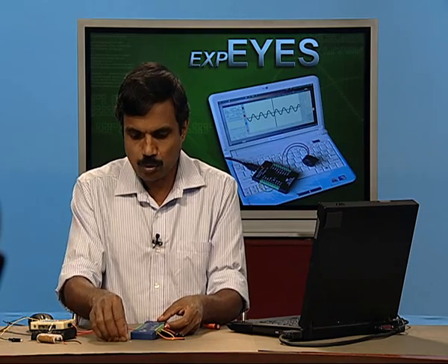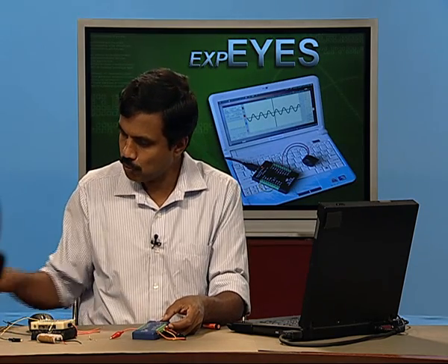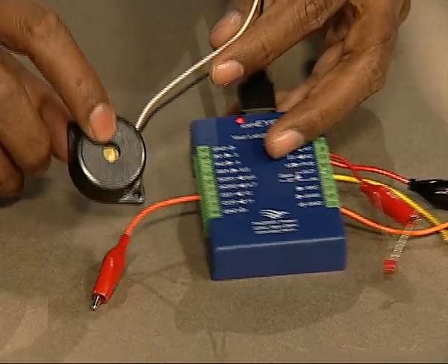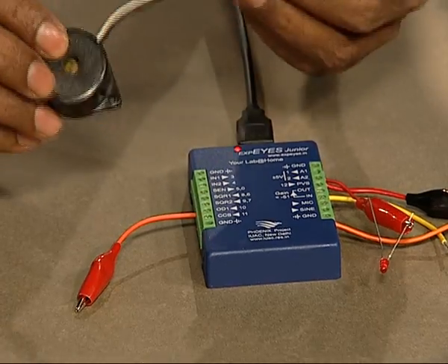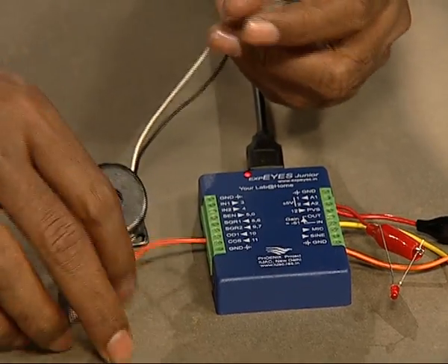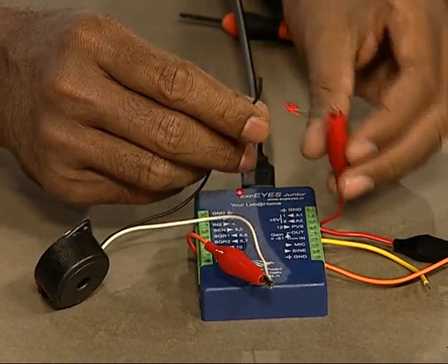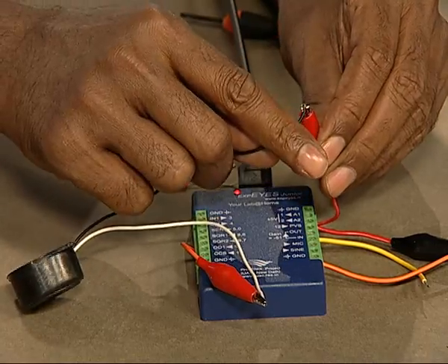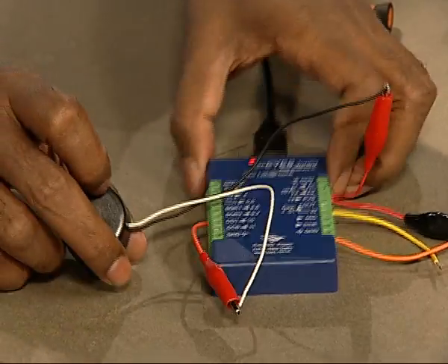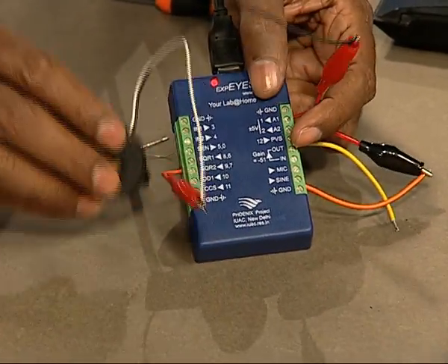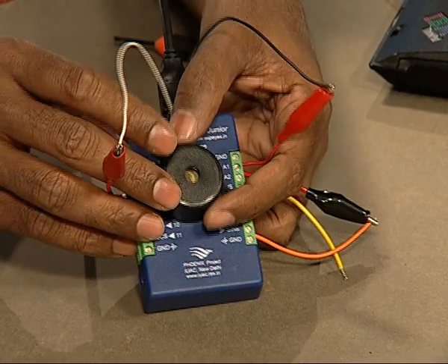So, this can be easily seen by connecting a piezo buzzer to that. If you connect a piezo buzzer like this one, then if you apply a frequency to the voltage to this, it will make this sound. So, let us connect the piezo buzzer to this point from here to ground. Now, whatever frequency you set here, you will hear the sound of same frequency from here.